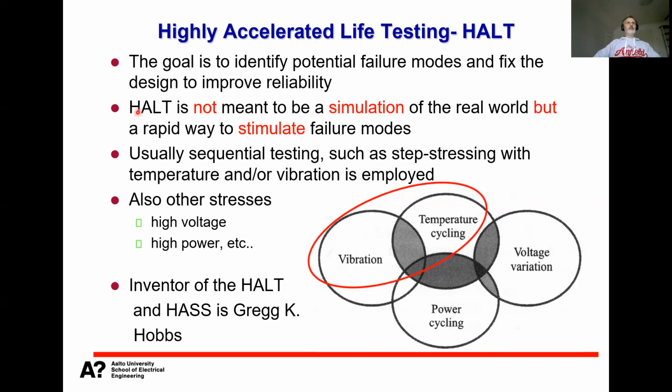Another way of putting it is that HALT is not meant to be a simulation of the real world, but a rapid way to stimulate the failure modes. Meaning we apply combinations of stresses which really show how high robustness our design has, and if we have any design mistakes.